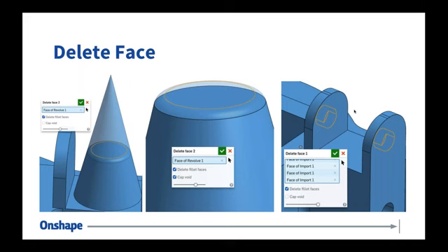If you imported a model and the surface is wrong, and a few of the faces need to be recreated, delete face is the tool that I would use to delete all of those faces. And then you can use our fill command or our loft command to patch those faces back into the geometry. But delete face, like the name implies, allows you to select faces from imported models and delete them. Whether they patch the geometry or heal the geometry afterwards or not is entirely up to you.